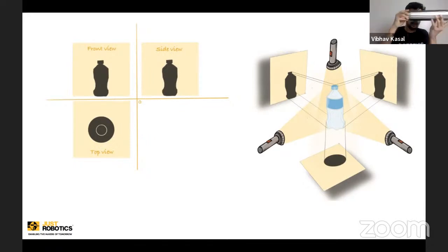You also have to superimpose what is on the other side. So it is 2 images, the front image and the back image superimposed. So you have all the lines that are there in the front and the back superimposed. So that is the top view. The same with the front view. You don't just write what is there in the front that you can see. What is there in the back, that also is there, and that is superimposed and kept. So that is front view, side view, and top view.